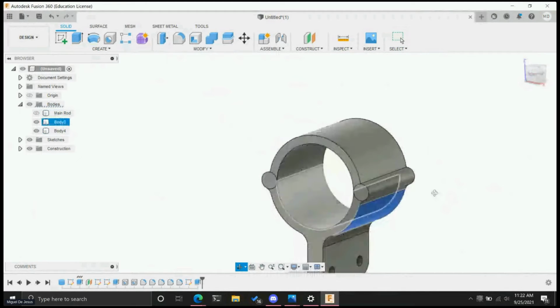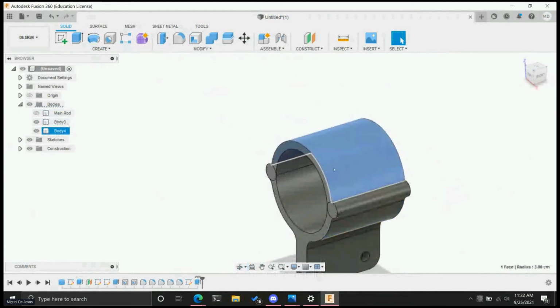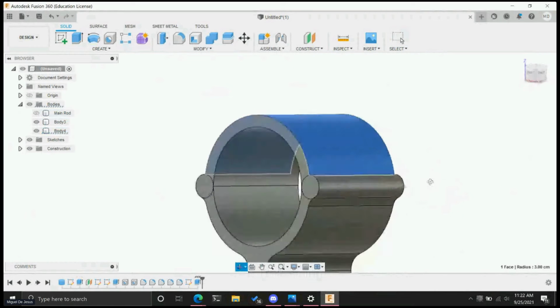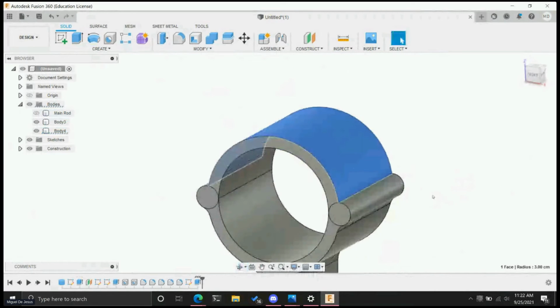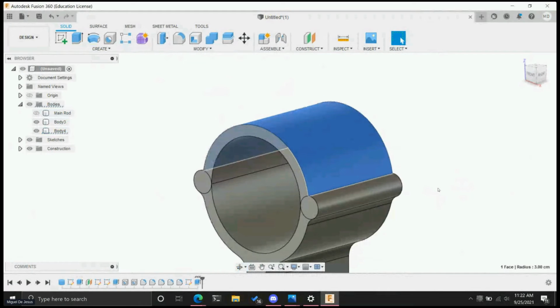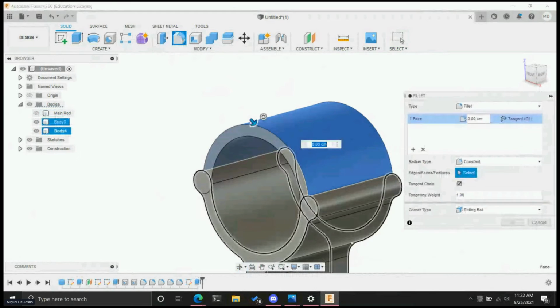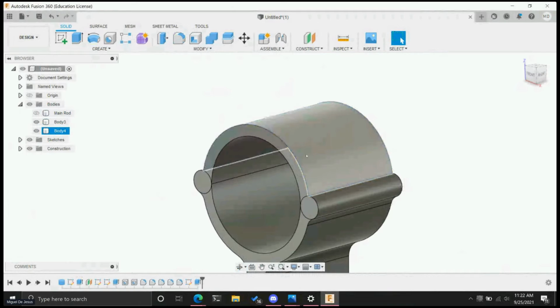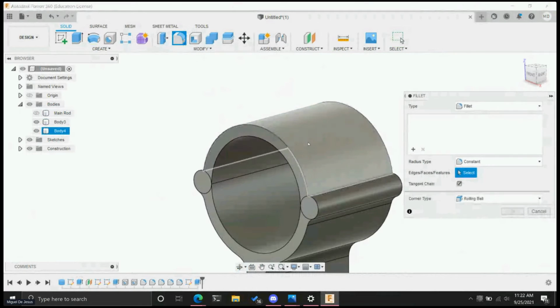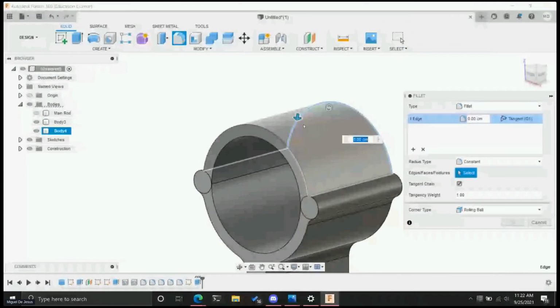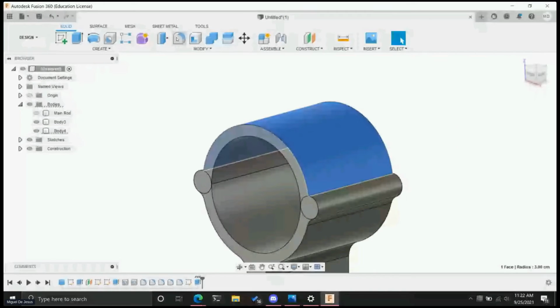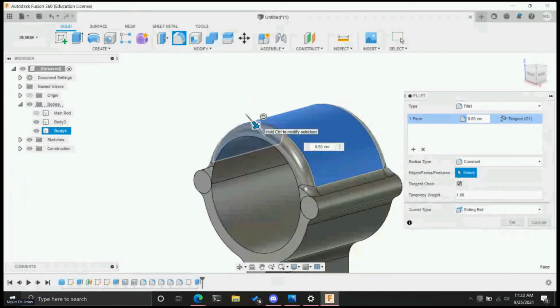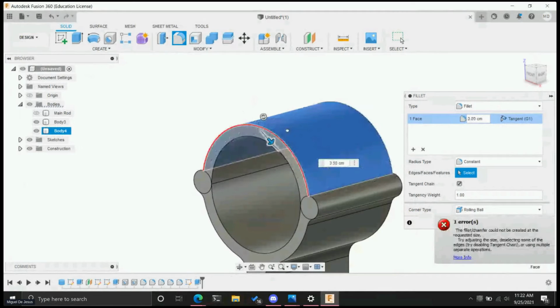Now, if you've ever seen any sort of hinge situation, you will know already that this is not really gonna work yet. We're gonna have to do a little more work to actually have a working hinge. But before that, I'm actually gonna just do the fillets here. If you select the whole surface instead of just a corner, you will have the fillet doing it for everything, which can get pretty wild.